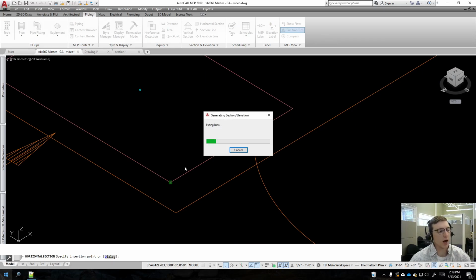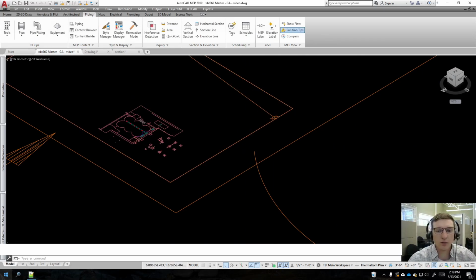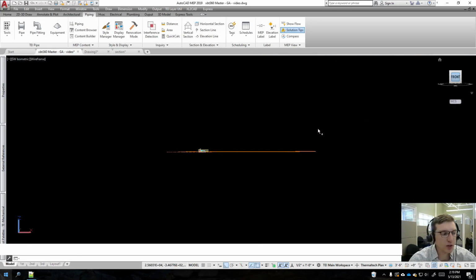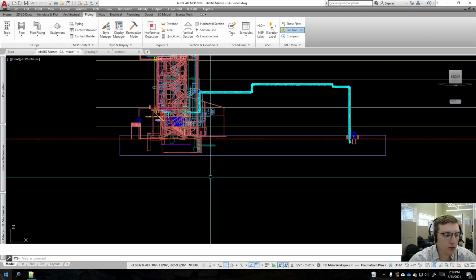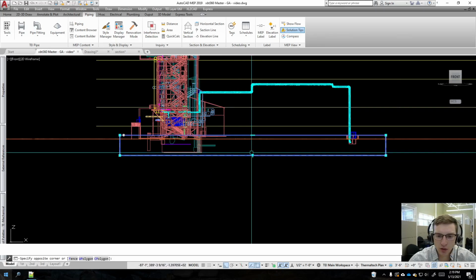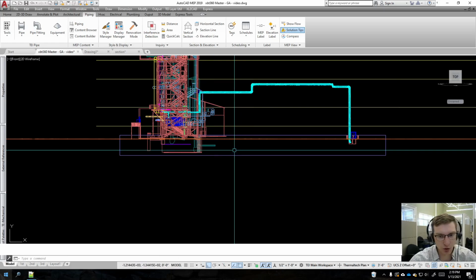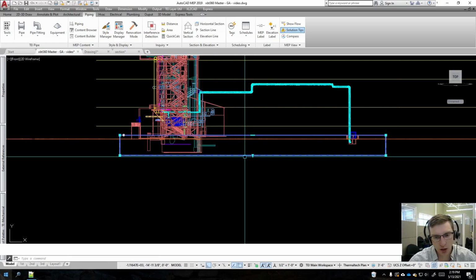We are going to have to edit that section cut down there. So we're just going to come down here to a front face view. We're going to make some edits, and then we're going to copy it up a couple of levels, and then we'll be done. Wrap this up. All right, we're going to need to change our UCS. If you aren't familiar with UCS, take a look at my video on that. Now, if you're having performance issues, just remember that you only need to do this once, and then you can completely unload your master here.